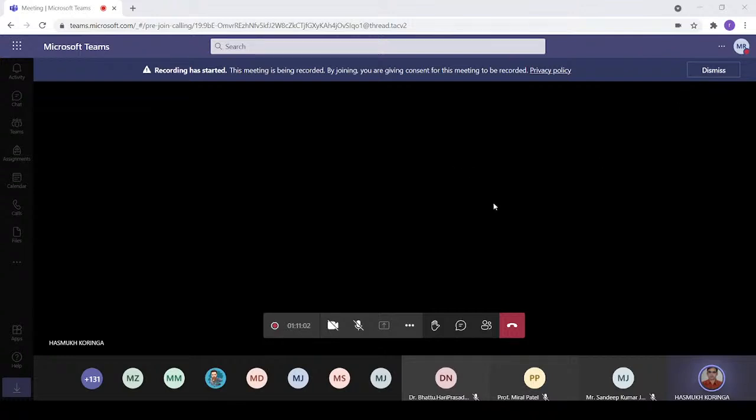As we know, FPGA is a lookup table based device in which the lookup table is nothing but SRAM. So for FPGA, it generates a .SRAM object file. And the CPLD is a non-volatile device, so it generates a programming file for it. It has programmable devices acting as a switch.